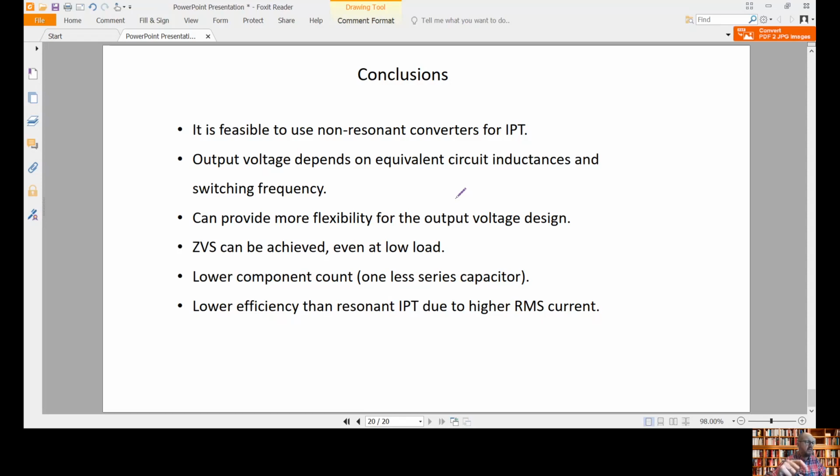At the input, the difference might not be so high, because at the end, at the input, we have part of this triangular waveform and part of this sinusoidal waveform, so the difference of EMI could not be so high.